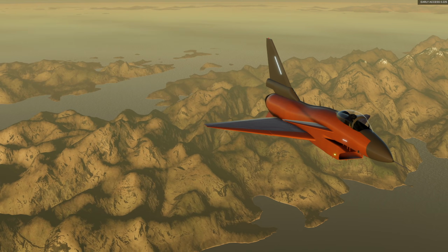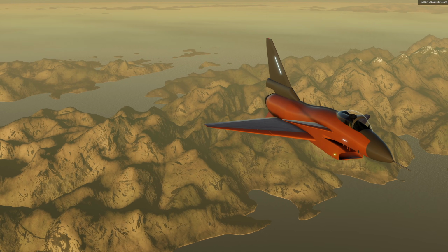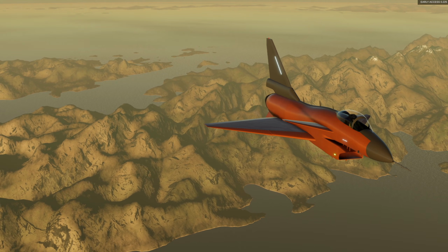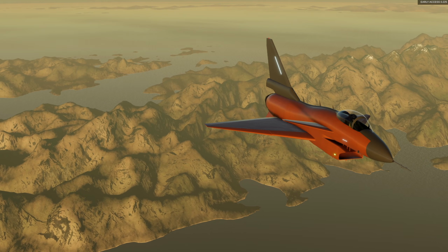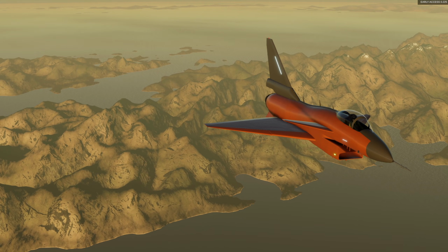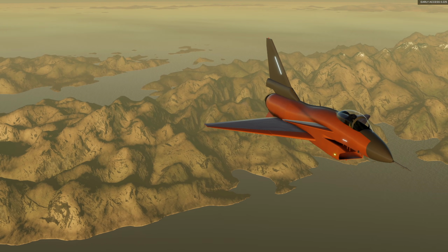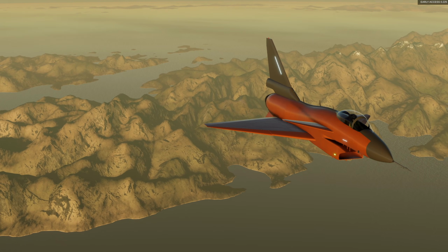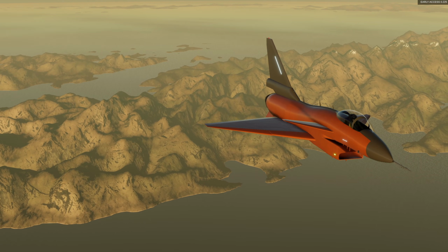It should be noted that in reality, reflexing the trailing edge upwards will not help delay the wing section from stalling for airfoils susceptible to leading edge stalls or thin airfoil stalls, as the entire upper surface will already be enveloped in the separated flow region as soon as the wing stalls.